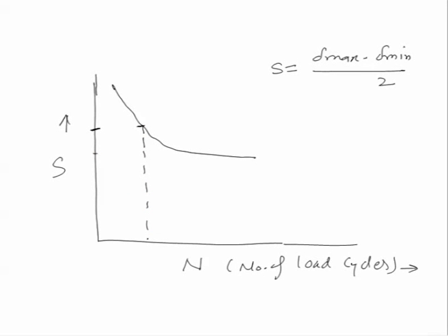If we keep on decreasing the stress amplitude, the number of cycles required for failure will keep on increasing, and this is the limit of the stress amplitude below which no failure will occur under fatigue load conditions. So, this is the schematic diagram showing the SN curve for steels, while in case of aluminum alloys, no such stress amplitude limit is obtained.